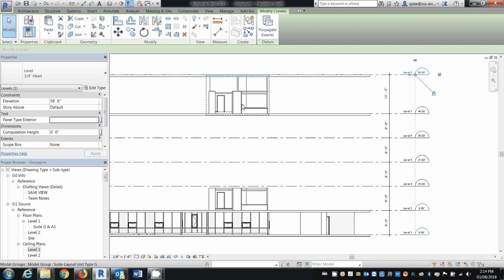In the past, if there was a level change, people would create a different group for that particular height. Now, if you have 4 or 5 of the same type, imagine how much time you have to waste updating all those changes, and consistency just goes down. Whereas this way, you keep the walls attached to the underside of the ceiling, and it's great, and you don't have to do much.